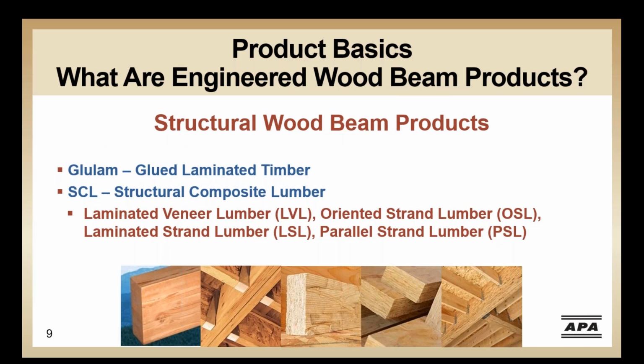Engineered wood can be described as any wood-based building material that has been improved physically by a man-made process. We essentially take the tree apart, sort out the flaws, grade the wood, and then engineer and reassemble the wood, orienting the grain so the finished product takes advantage of wood strength properties. Today we'll be talking about a group of structural wood products manufactured using either veneers, wood strands, and solid wood that are commonly used as beams and columns.